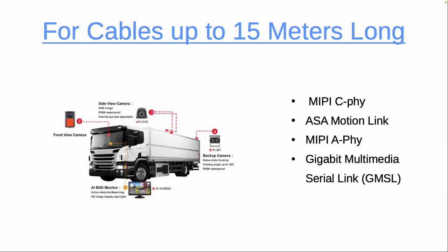The other one that's interesting out of AMD is Gigabit Multimedia Serial Link, and why I like that is the return path, the controls, the low bandwidth one, can be on separate wires from the video signal, and so that simplifies the electronics for low volume prototypes.